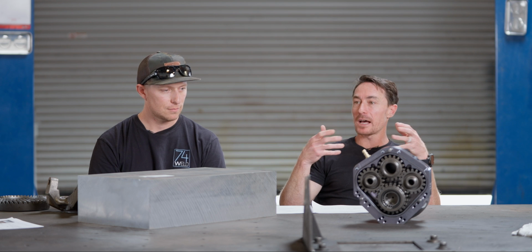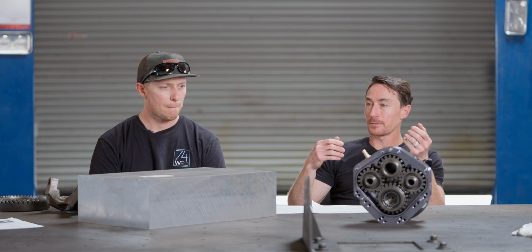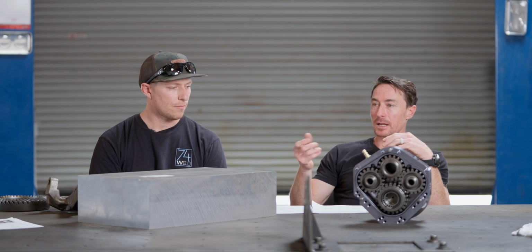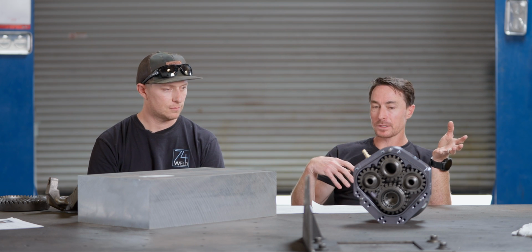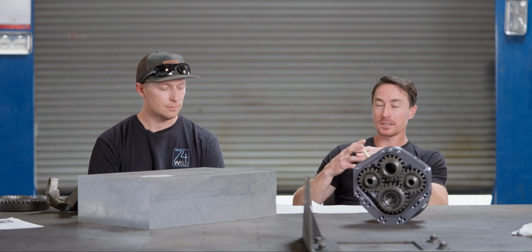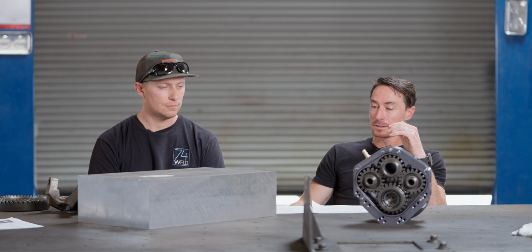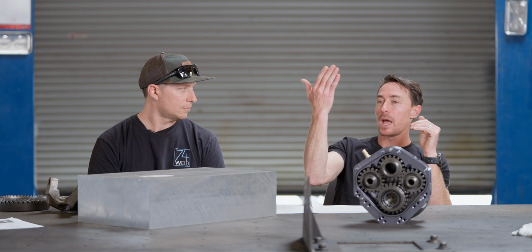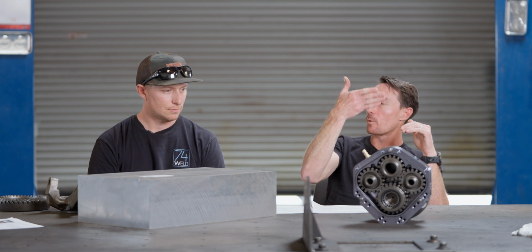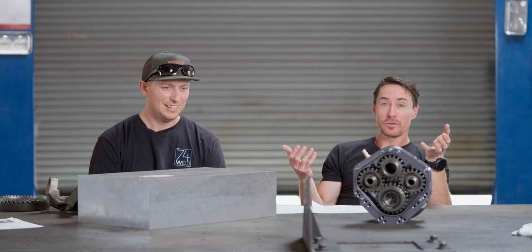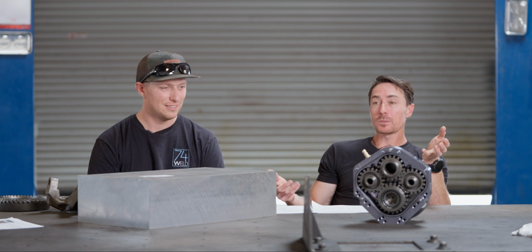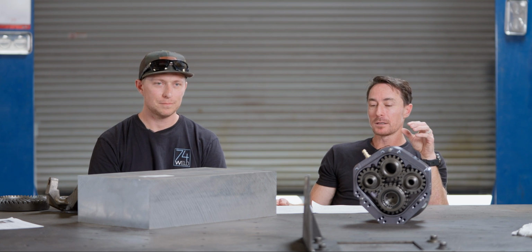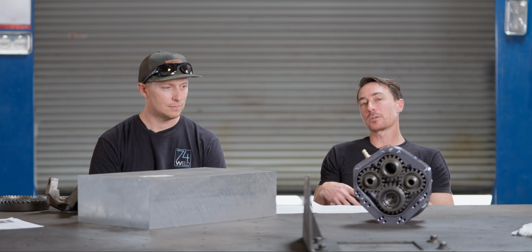And you'll see iron castings used. A good friend of mine was an engineer at ProComp and designed a lot of their uprights, and they would use ductile iron for these castings, and they're extremely strong. And he would tell me, when I did this stuff, we did brake tests, and that spindle or that upright would bend 4 inches before it snapped. That's insane. It's pretty awesome. It's strong material, but this comes down to what are the nuances that you care about, and you can design around a lot of this stuff too.